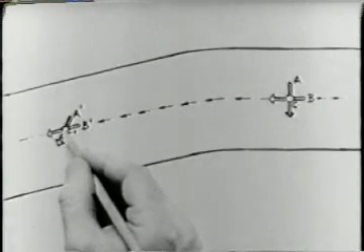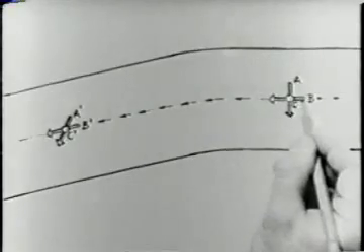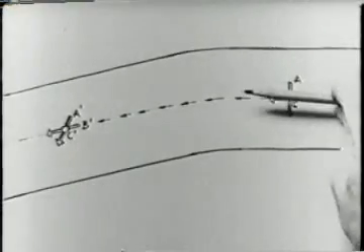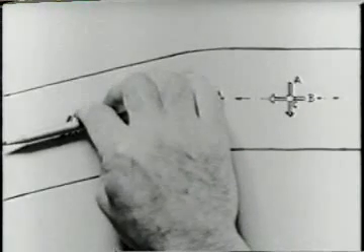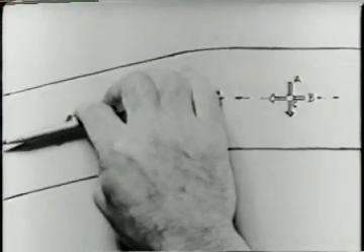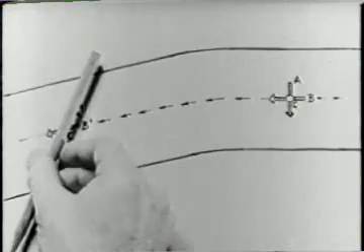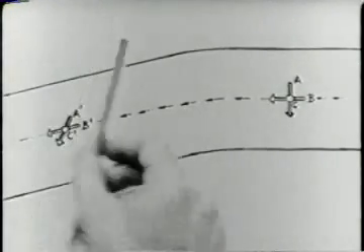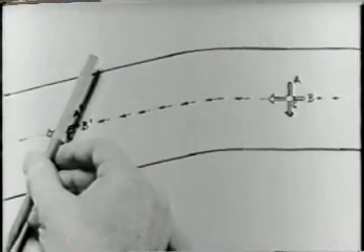The vertical component of vorticity is connected with the turning of the lines A and B. Line B follows its streamline and therefore rotates in a counterclockwise sense. Since the vertical vorticity remains zero, line A must rotate clockwise by an equal amount. This clockwise turning of line A into position A prime requires that the velocity at the inside of the bend be greater than the velocity at the outside.